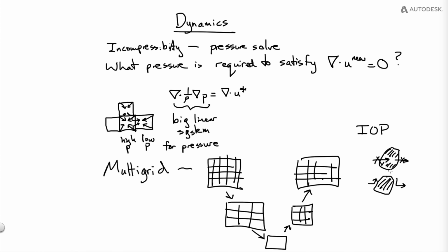And I can do that locally, just around the boundary of the solid, but that may screw up the volume conservation here. So then if I go back and fix the pressure, and then I go back and do this, if I iterate between that, it actually does converge to the right solution. And that's a parameter you can control depending on how much fidelity you want. But of course, the more iterations back and forth you go, the slower it is.